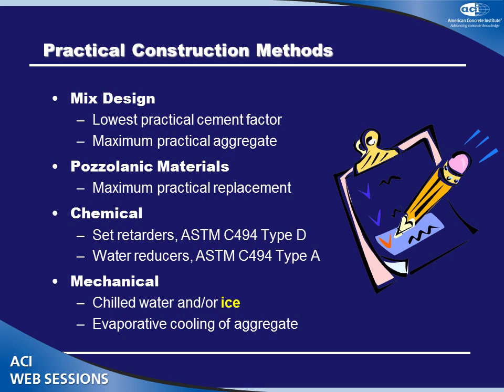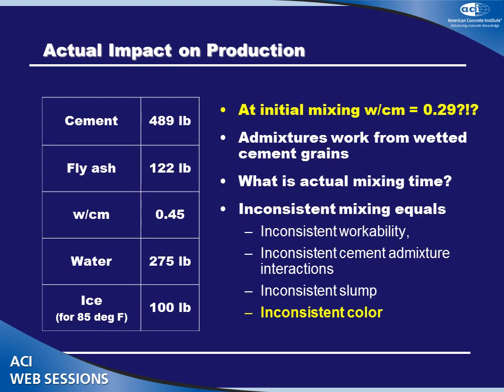Well, let's talk about that a second. Let me give you an actual mix design on an actual project where we had this issue. So here's the mix design with the composition of it and the weights here. And I want to highlight for you the ice that was necessary to achieve the 85 degree temperature specification. We had to put in 100 pounds of ice per yard,